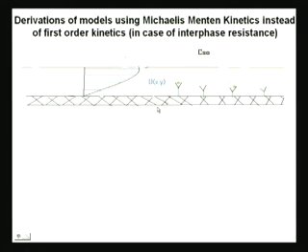The convection diffusion reaction equation using boundary layer theory is not something you can solve analytically for a nonlinear reaction. It is not even something that you can solve analytically for a linear reaction, let alone a nonlinear one. So, obviously, that is ruled out if you want an analytical solution. The one that we are left with is the use of the mass transfer coefficient. So, let us do that.